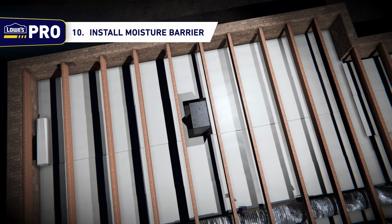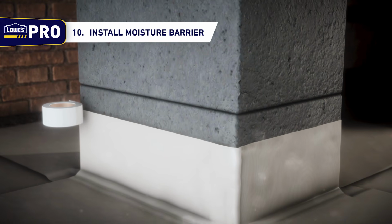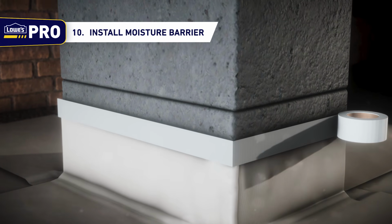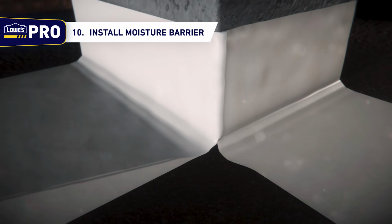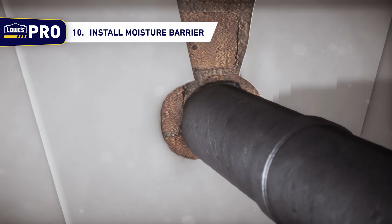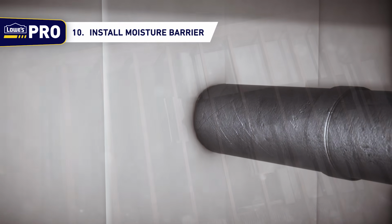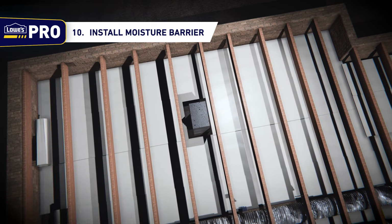Step 10. Install moisture barrier. For a partial encapsulation like this one, start by wrapping the base of all piers in the crawlspace with pieces of the moisture barrier. Go at least 4 inches above the ground and tape tightly around the piers. Cut relief slits into the moisture barrier at the bottom so it'll sit flat against the ground. For pipes, cut out a hole in a piece of the moisture barrier for the pipe to fit through, and then tightly tape it around the pipe. Once you've finished this detail work, line the entire crawl space with the moisture barrier.